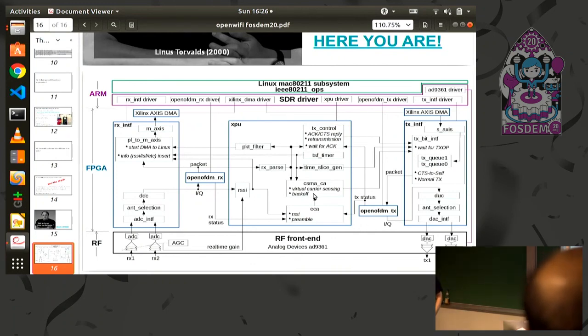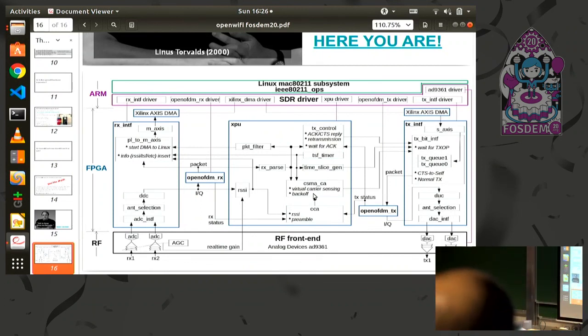Okay. For the TX path, actually there are two queues. Linux asks the chip to have at least 4 queues, but currently we implement 2. It still works. All the packets come from Linux. They cannot go outside immediately, right? First they go into the queue, and the CSMA engine will decide when is the right timing for the next packet to go outside.